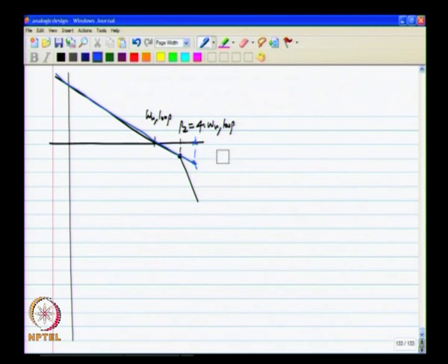Here it becomes steeper, and if you have 3 extra poles, it falls down even steeper, but for the same phase margin we computed that they should be at 12 times the unity loop gain frequency.